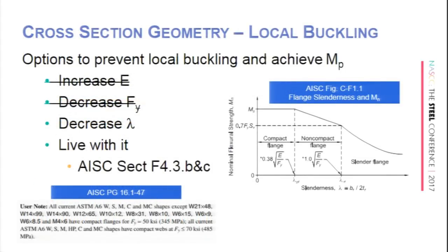I do think I want to go back here for a minute. That note at the bottom: in the world that I now live in, nuclear structures, I look at plates that are not typically A572 grade 50. Some got substituted out as A572 grade 60, some as grade 65. They want to actually look at that within the specification for the 2022 spec.